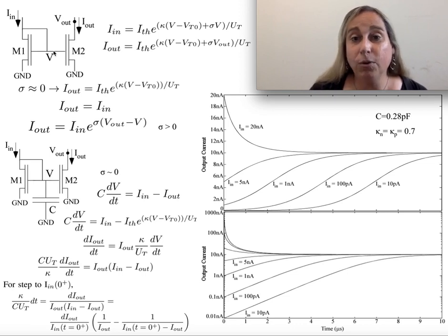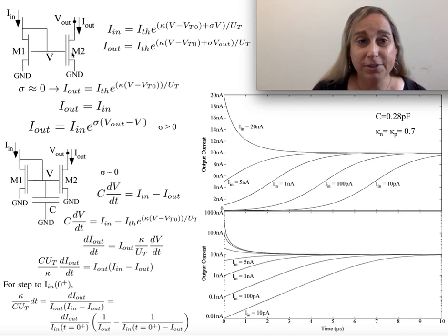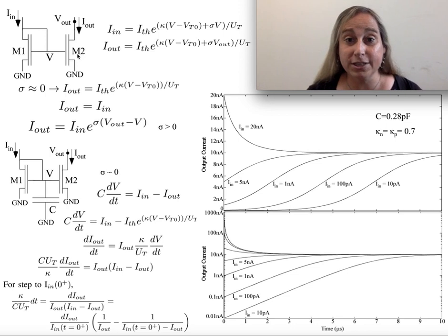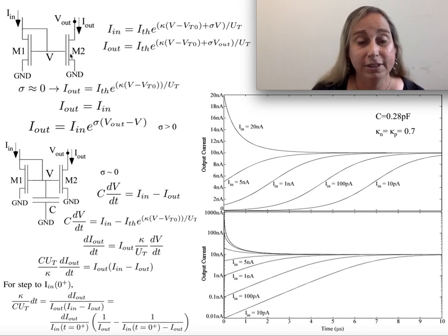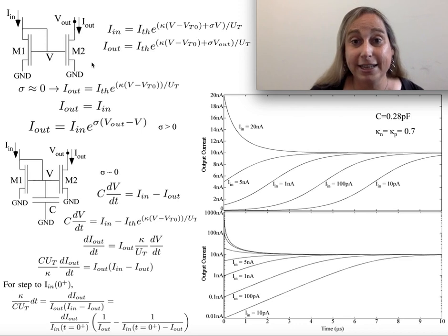And at its very core, it's a case of I initially take this input voltage, it sets up a feedback such that that voltage node V finds the steady state such that this transistor M1 sinks that current and pulls that current down. And then you put the same element, M2, and we're going to consider them to be identical for the moment, will then allow you to pull. It means I put the exact same voltage that pulled that current, so I should get exactly that same current.